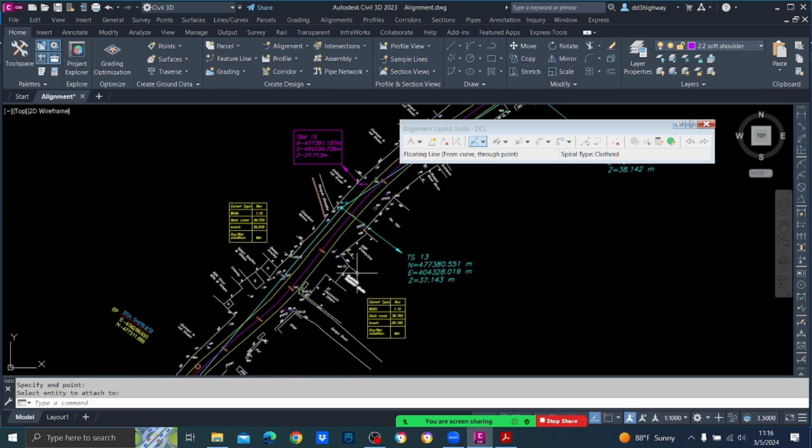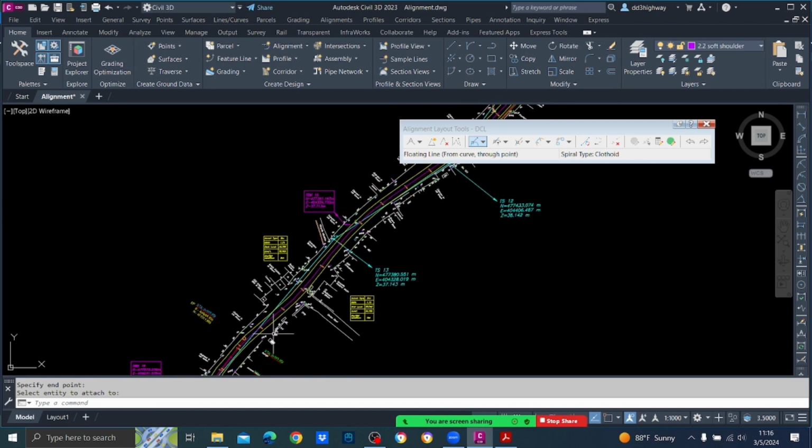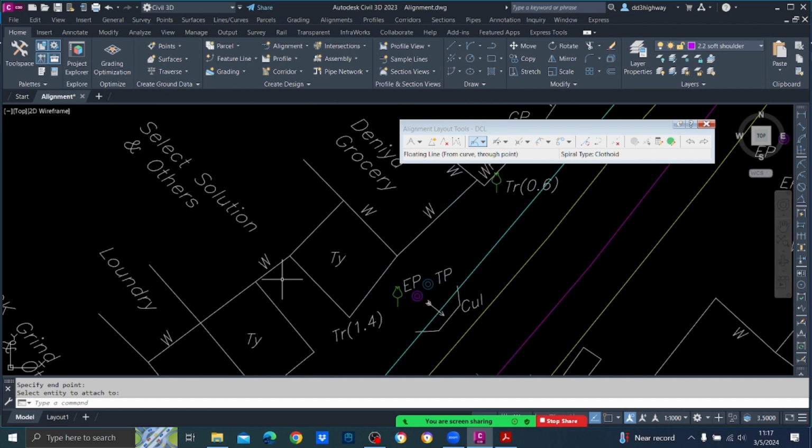Can you see there? Now this is having a lot of compound curves, sorry, reverse curves. This way it goes clockwise, then anti-clockwise, again clockwise. Now one thing you can do, that depends upon your strategy in design, is replace everything with one straight, but you have to check. Now what are these things?